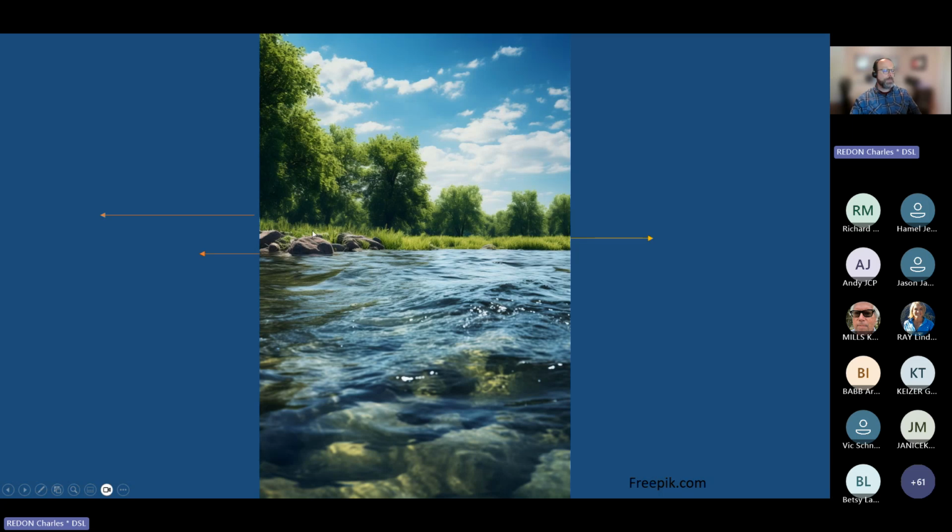And so up to this level might actually be the boundary of the river for the purposes of removal fill law. And in some cases, you have areas that these might be trees that are staying 3 feet up the trunk because every winter for weeks or months at a time, they're underwater. Well, that's actually ordinary high water. And so for the purposes, again, just of removal fill law, removal or fill of material within those boundaries is going to be it. So it's determined case by case. In some streams, it's very clear. It's top of bank. The stream never comes out of those banks. That's ordinary high. But in some flat areas or areas that are subject to huge variations, it might be much, much wider than you would see at a normal time of year.